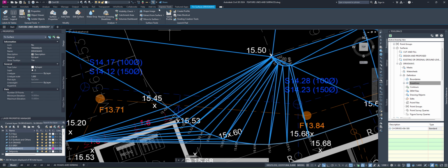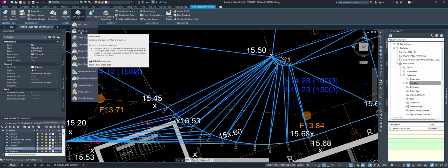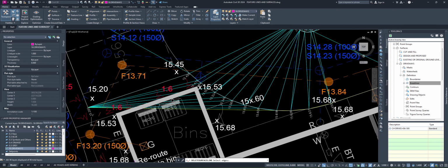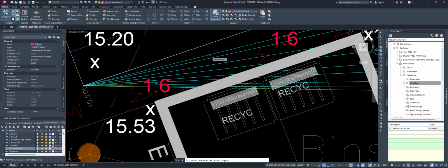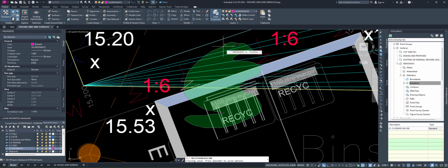There you go. Now if you go in that edit surface drop down, it's going to give you a couple of different options. One of them is delete line. This is the tool which allows you to trim the triangles. So if I click on delete line, then if I come down here, using the mouse, holding the left button, dragging to the left, so it's that green semi-transparent color. I'm gonna go over all the lines just like this. Okay, and then I'm gonna release the button.